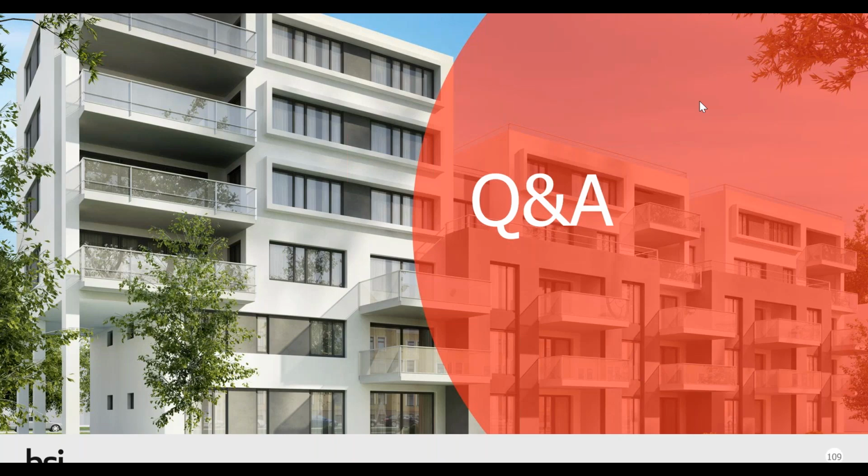Added to that is the question of whether laminated glass is combustible as such. The jury's out on that, I think. Is the interlayer combustible? Yes, certainly certain types of interlayers are combustible. PVB is known to be combustible, but there are other interlayers. There is research into the use of other interlayers going on around the industry. The government has commissioned its research, so hopefully over the course of those two parallel activities, further guidance will come out.